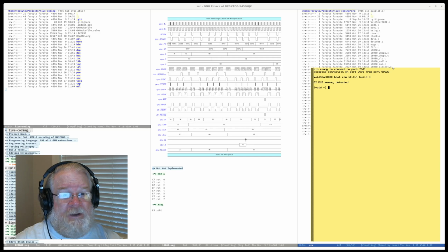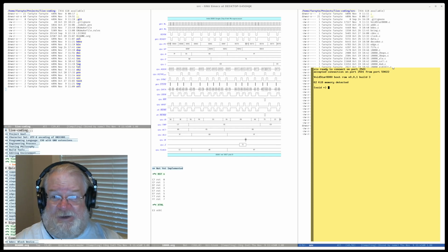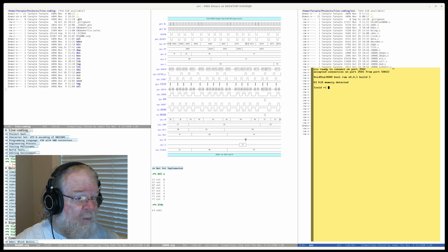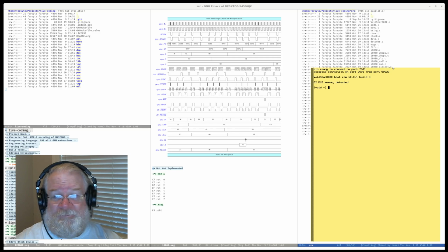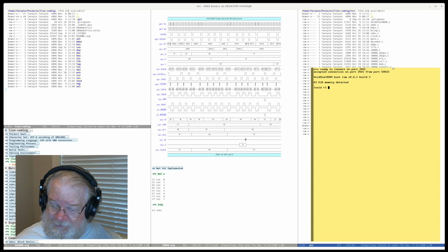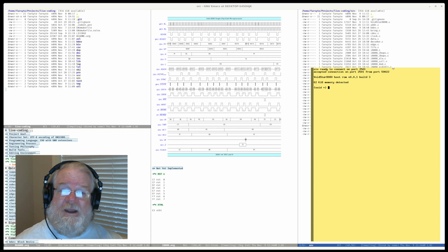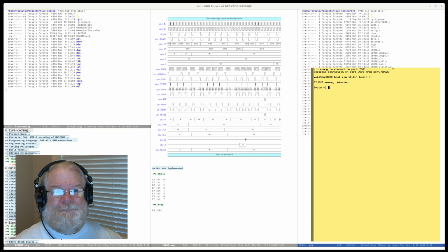instead, what I'll do is I'll write a simple boot ROM that allows me to boot from one of my disks. Okay, that's really all it does. I mean, I can halt, I can boot from disk, and that's it. And all the disk boot is going to do is it's going to select the appropriate drive 0 through 3, and read in the first 128 bytes. So the first sector of the first track. So it's sector 1, track 0, gets read into memory, and we start it running. Okay.